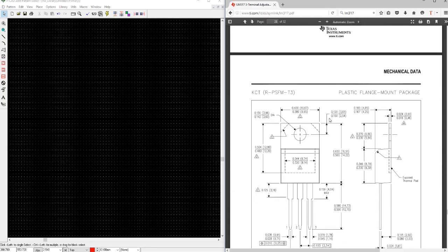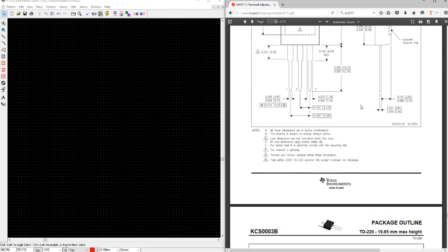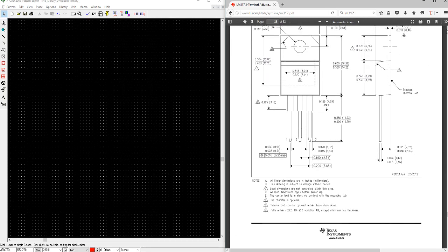So that supports exactly what I said, that most surface mount components are created on a millimeter pitch, and all through-hole components are generally created on a mil pitch. So whatever we see the smallest number, that is the number that is in inches. Between brackets, we see the millimeters. So just have a look at the bottom of each document. You will always find that.